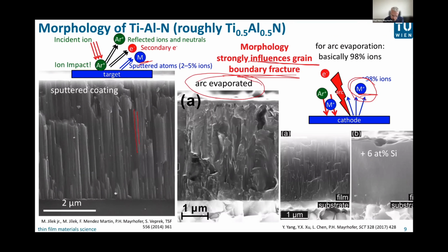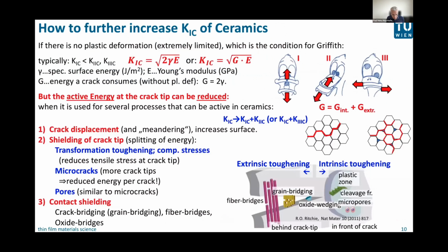That ends up with a much smoother, less grain boundary failure, and that by itself increases K1C. And using other elements that can strengthen or increase the cohesive strength of the boundaries is extremely positive in that. So that is one process.